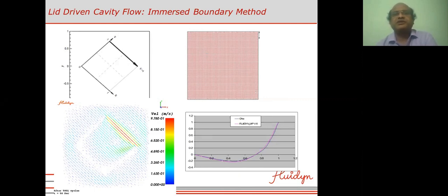So, for example, you take this mesh here, and the lid is modeled like this. That is, a mesh for the surface is created like this. You can see that, and velocity is applied. So you can see that the normal mesh is very simple. It doesn't have to be inclined. It's like a normal Cartesian mesh, but we can put a sloping surface there. You can see the velocity profile here. The lid is moving in this direction, so it induces the correct recirculation in the domain.